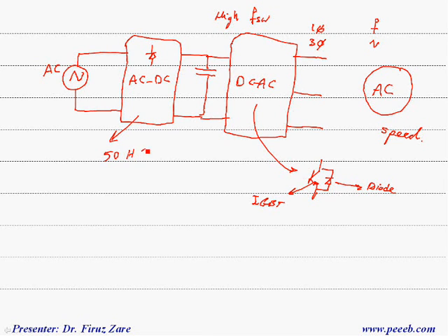So this is the power converter for an AC drive system, and in most applications, we don't need a filter. That means we can directly connect it to either a single phase or three-phase machine. But for some applications, especially if there is a long cable which may resonate and create over voltage, we may need to have a filter between the drive and the AC machine.